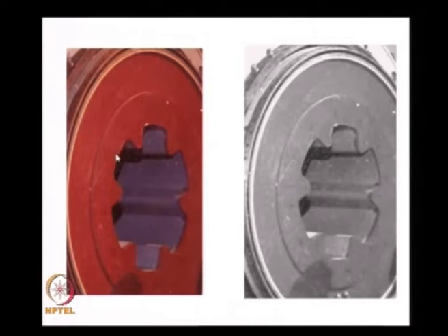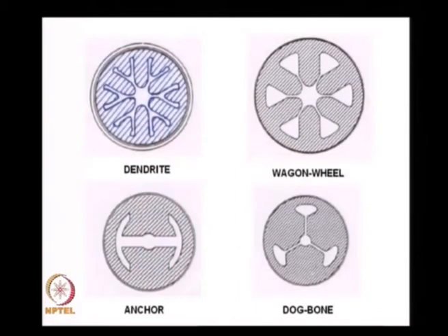The minimum thickness is what we call the web thickness. The same grain I show over here just to make sure we understand. You find that the inner surface has a projection here, a valley here, again a projection here. This projection is all along the surface, and the grain burns radially, that means it burns into the grain in this particular fashion, and all along the surface keeps retracting like this. And I will consider a few examples such that we are very clear how to calculate these things.